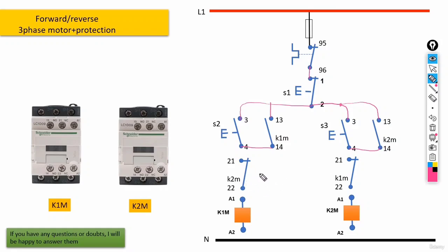The newly added item here would be this normally closed contact that we set in the path of the electrical currents in both contactors. What does this exactly mean, though? Well, we got a contactor here called K1M. Now, this contactor has a normal closed contact which is now set in the electrical currents path here.